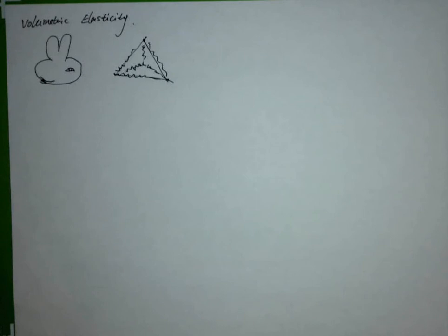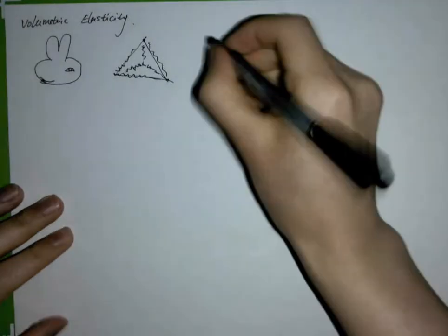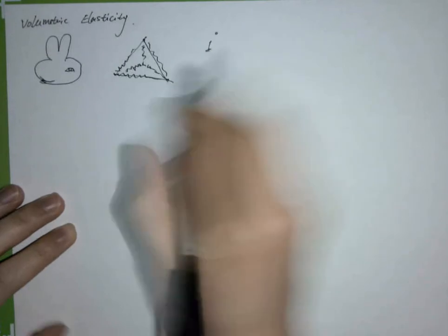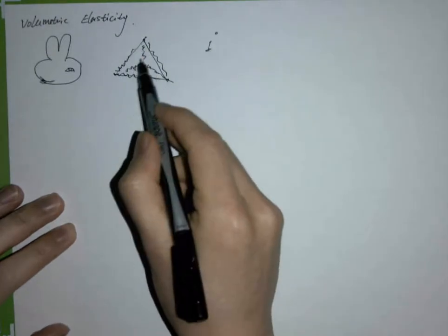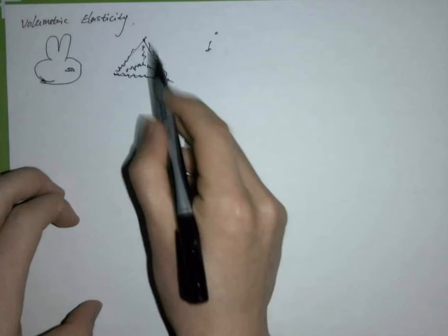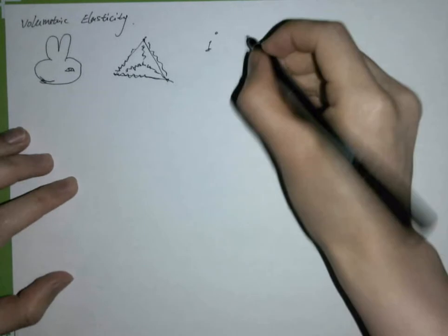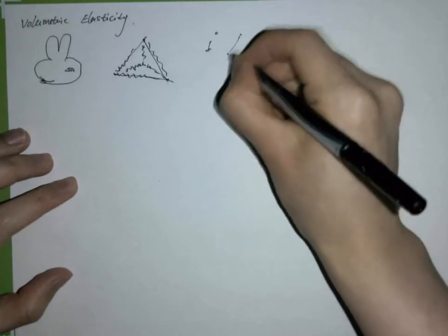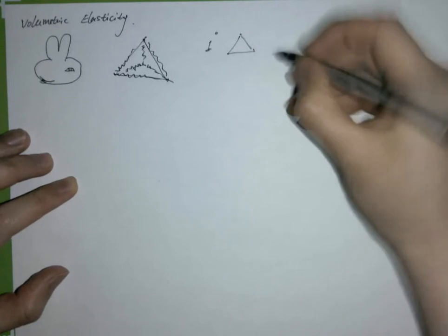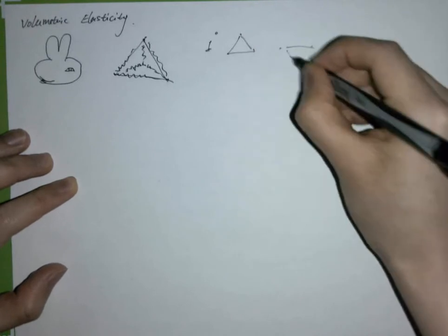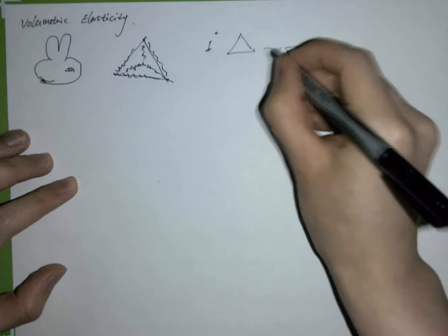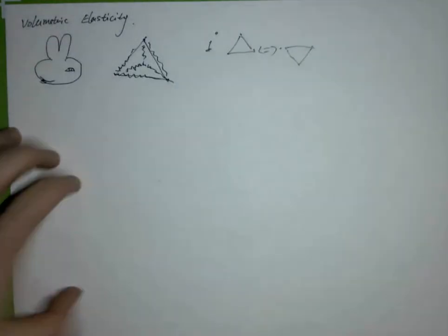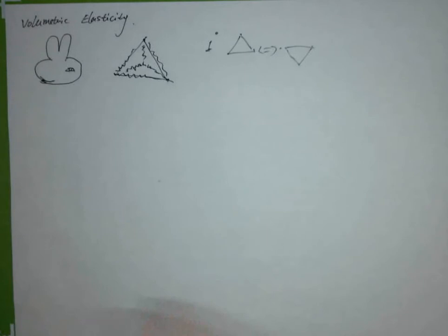The first one is that all the springs are not aware of the existence of this element. If I draw in 2D, I can make a triangle using 3 springs, and if I flip the triangle completely, all the springs are still in their rest pose. So there's basically no force at all. So if you flip something, you break some tetrahedron, then it will never go back again. All right, so this is the first one.